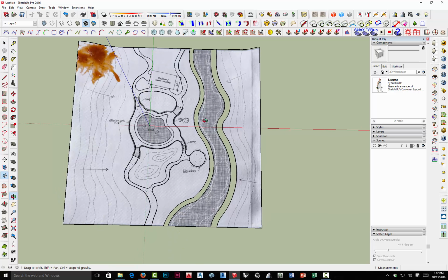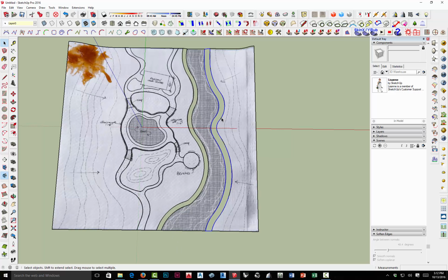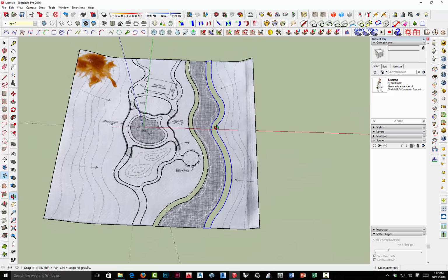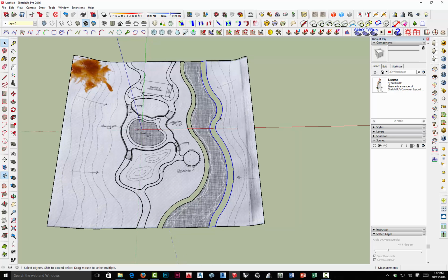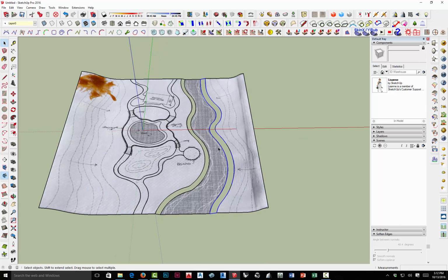So I'm going to tilt it up in the surface, drag around, select it, hold Shift and Control to subtract from the selection, and just right click over that and make sure that the only thing selected is that area. This is also why that initial geometry is super important. If this is well-formed, simple geometry, connected at all the endpoints, this will work every time. If it's badly formed, if it's disconnected, then it's not going to work. You have to have a certain amount of digital craft while you're doing this and really be careful with how you put things together. Digital tools are really amazing, but they're not very forgiving.